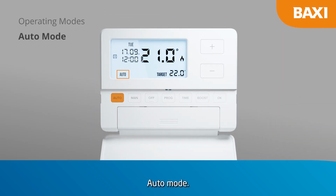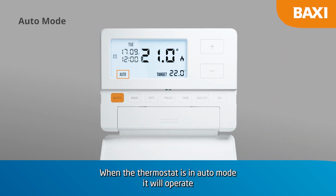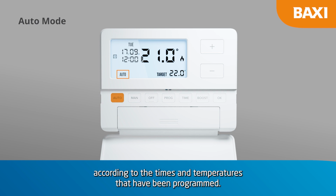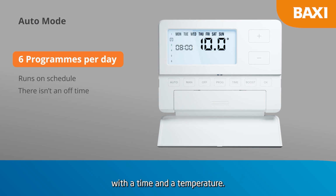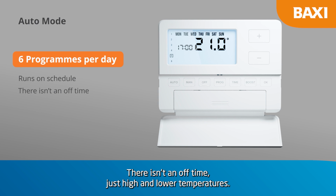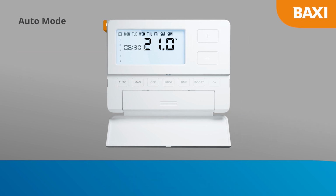Auto mode. When the thermostat is in auto mode, it will operate according to the times and temperatures that have been programmed. You can select from 6 different programs per day, each with a time and a temperature. There isn't an off time, just high and lower temperatures. Example, to have the heating turn on at 6:30 AM until 8 AM for 21 degrees.